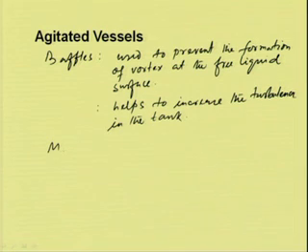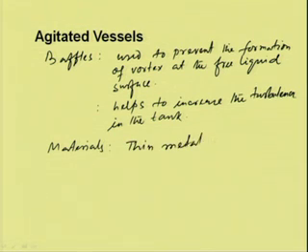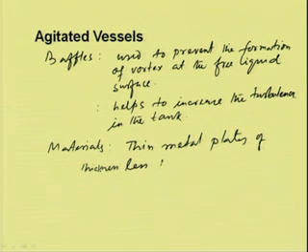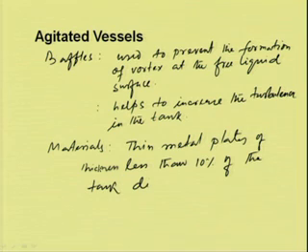For the baffles, we can use thin metal plates of thickness less than 10% of the tank diameter.